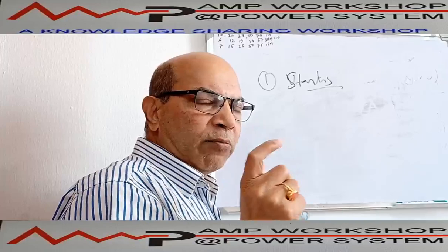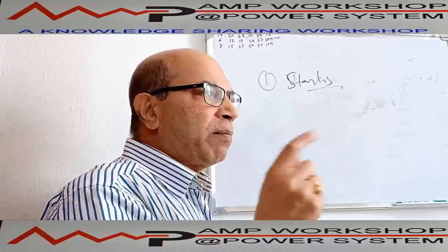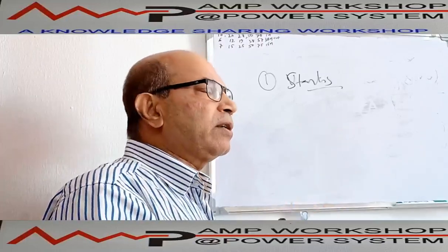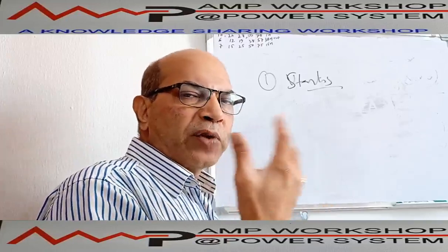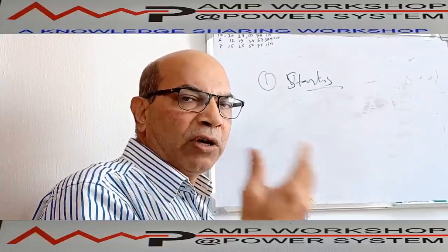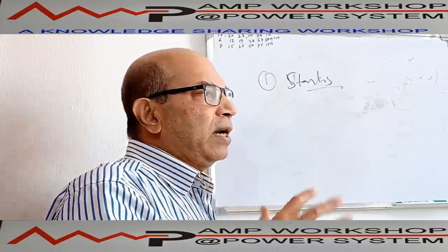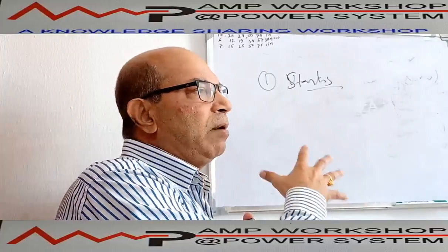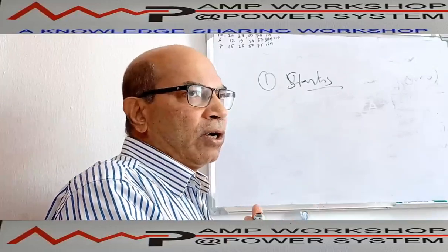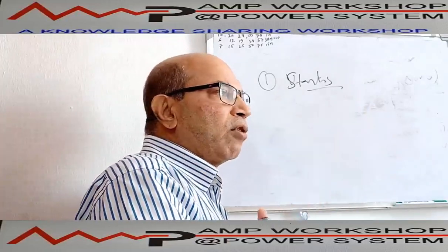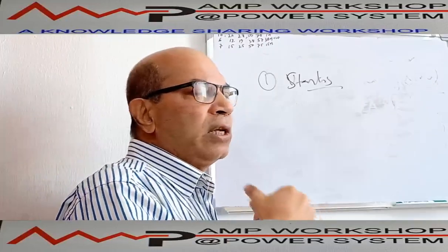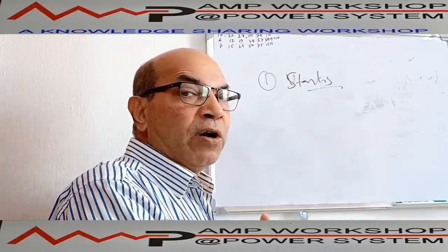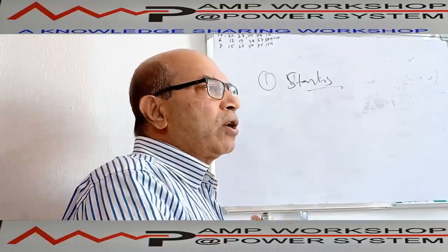that means 20% voltage drop we are allowing from the switchboard to the motor during starting time, because at starting time motor current is approximately 6 times in case of DOL starting. So with the 6 times current, we have to check whether the cable voltage drop during motor starting is within the 20% or not. If it is less than 20%, that cross section is very fine. If not, then we have to increase the cross section area again in case of motor cable. But normally we do not consider 20%.